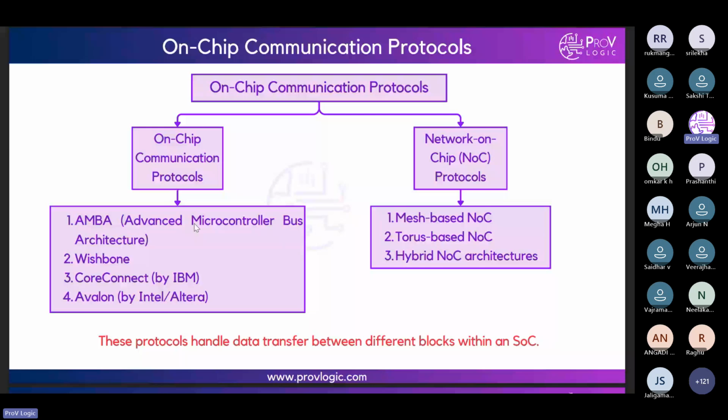In between these two, to synchronize without any data loss, we use a bridge. That bridge is specially designed based on AXI features and APB features. It's like a FIFO, but a FIFO has a different structure. This bridge should get the inputs of AXI, based on AXI features.